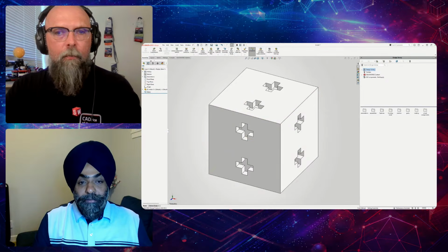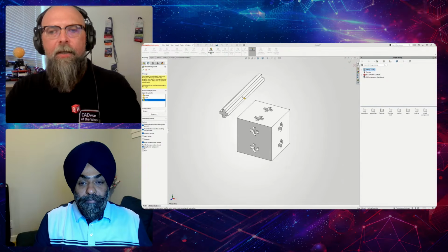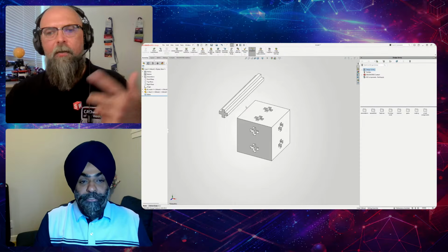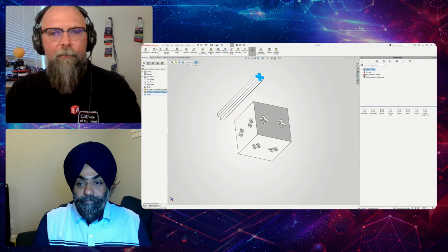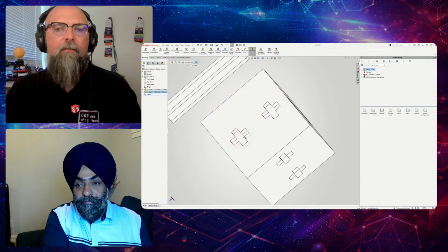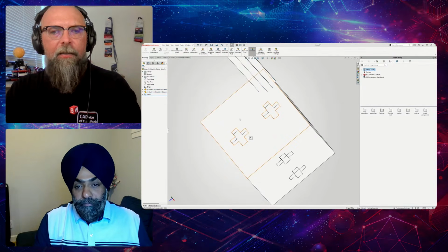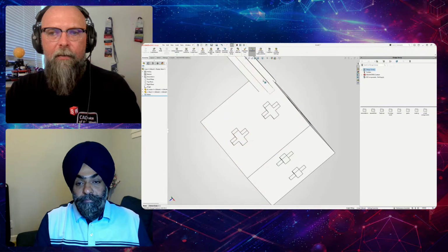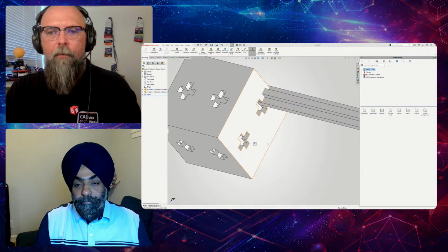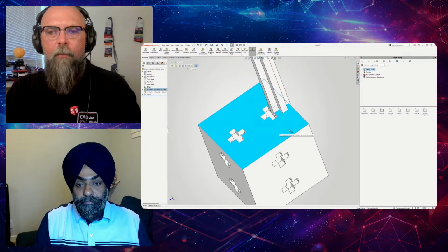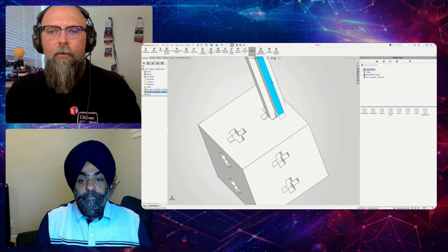So now we need to insert a new component. We need to insert the stud here. Again, now we're back with Legos, because we have the box and then want to insert this. The easiest way is to use what we call mates, which makes the model stick together. So now I'm mating to the point where I want this, and then I can mate this one. Right now, the selected component is fixed, but this one can still move in this direction. So we don't want that.